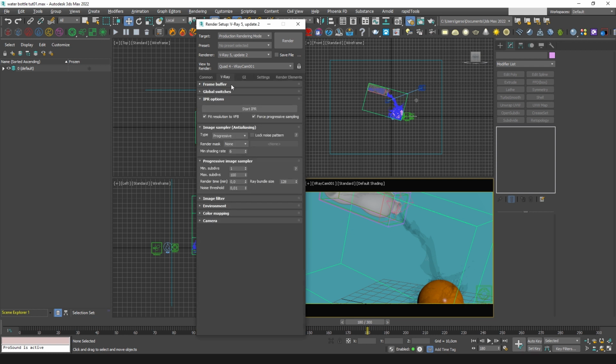Use the denoiser because here I reduce the samples to 8, here 25, so we will need the denoiser, and this depends. Some cases you need it, some cases you don't. If you use the denoiser, maybe you cannot turn this on. But if you don't use the denoiser, you sometimes have to turn this on.